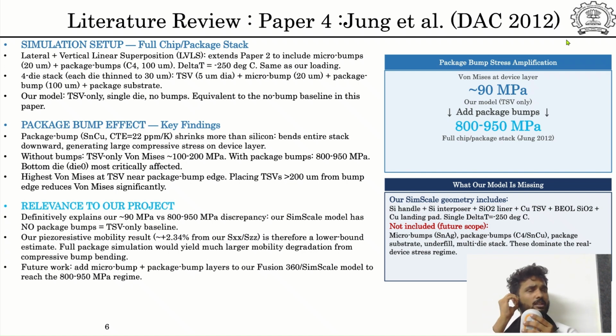Now coming to the key finding of this research paper: without package bumps, the stress is around 100 to 200 megapascal, while with package bumps, stress increases to 800 to 950 megapascal. This clearly shows that package bumps significantly amplify the stress. Also, the bottom die is most affected. Stress is highest near package bump edges. Increasing distance from the bump reduces stresses.